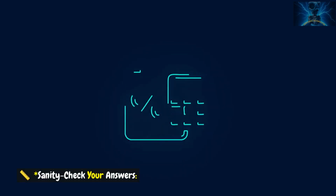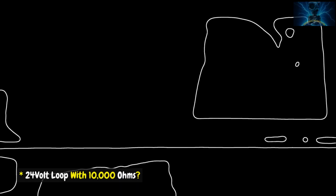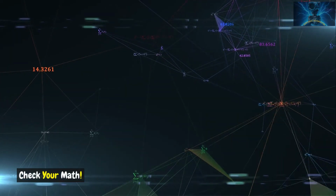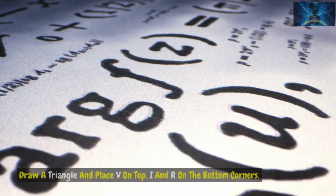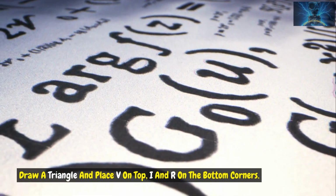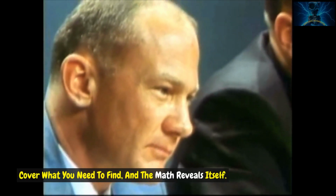Sanity check your answers. Amps smaller than milliamps? Red flag. A 24-volt loop with 10,000 ohms? Check your math. Don't guess, calculate. Pro tip: use a formula triangle. Draw a triangle and place V on top, I and R on the bottom corners. Cover what you need to find, and the math reveals itself.